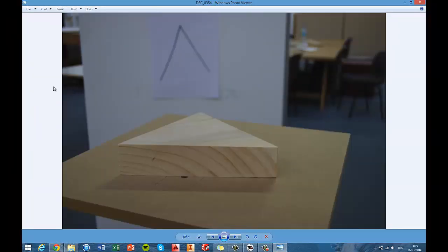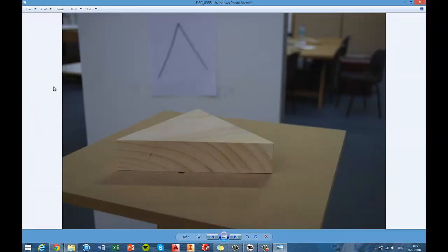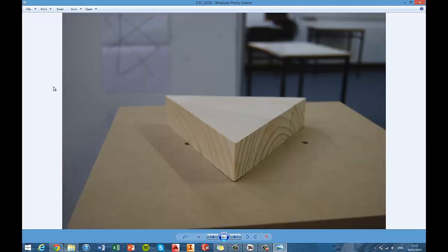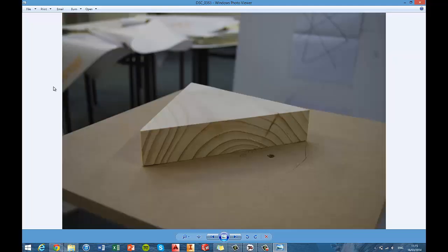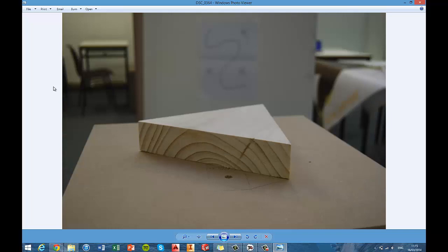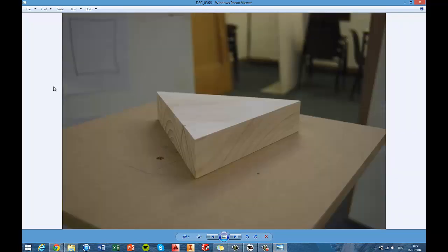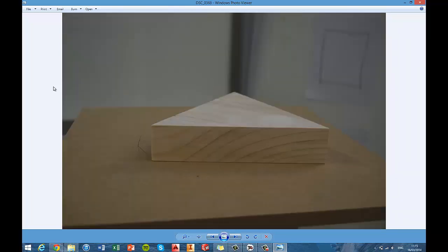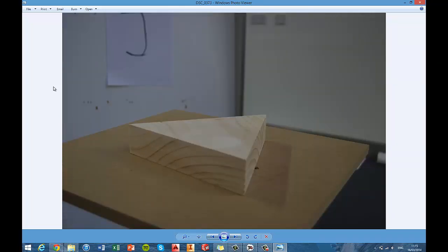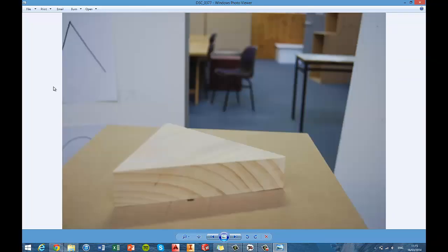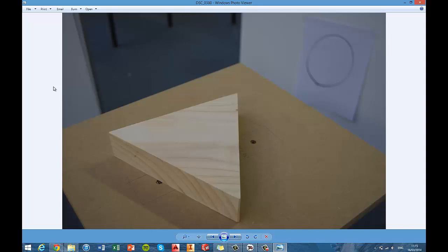For this project, I took about 25 photographs at a low angle and about 20 at a high angle. The number of photos that you take may vary depending on the size of the object that you are using. Autodesk recommend that no more than 70 photos be used. However, if you upload more than this, it still seems to work fine.